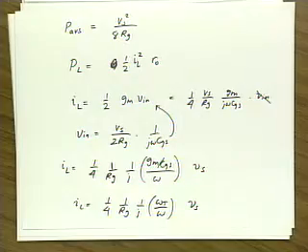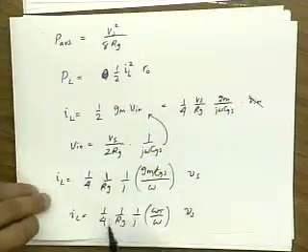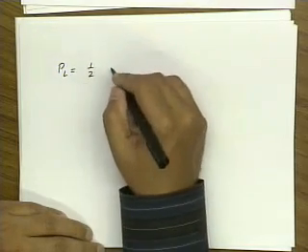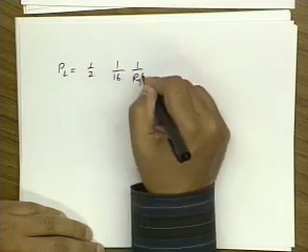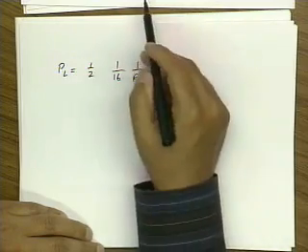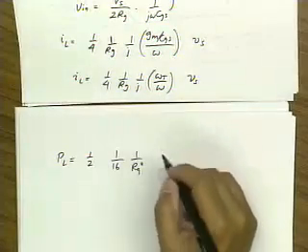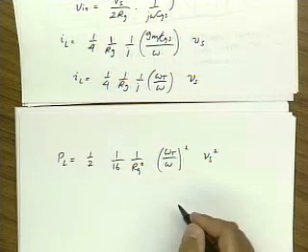Okay? So let's substitute that into the load. So I just take IL squared. So power to the load is 1/2 IL squared. So I have 1/16, 1 over Rg squared. And I'm taking magnitude, so j goes away. Omega t over omega squared, Vs squared.